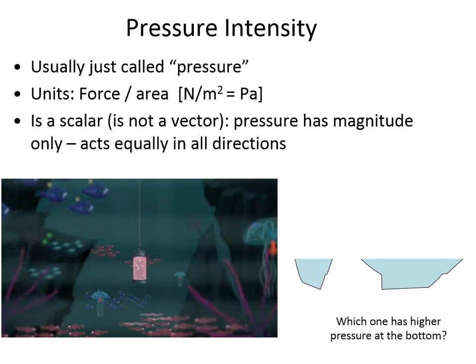And so with having said that, which one of these do you think has a greater pressure at the bottom? The reservoir on the left, which is smaller and there isn't as much water in it, or the reservoir on the right, which has a lot more. They're the mirror image of each other, but the reservoir on the right is much wider. So if you're at the bottom of each reservoir, how do the pressures compare? Same. That's a trick question.